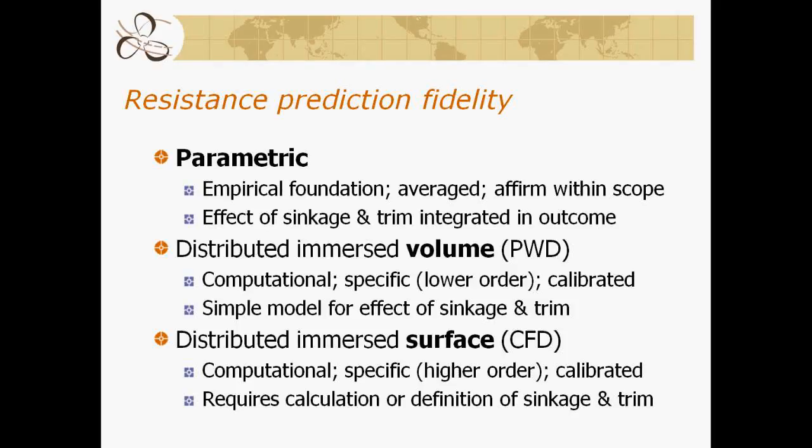Now, a distributed immersed surface method, CFD, is also computational. It's of a higher order, but specific to a particular geometry. It also is typically calibrated to empirical data. And it requires a calculation or a priori definition of the sinkage and trim. That's an additional variable that must be resolved in the CFD calculation, which is included in the other two.